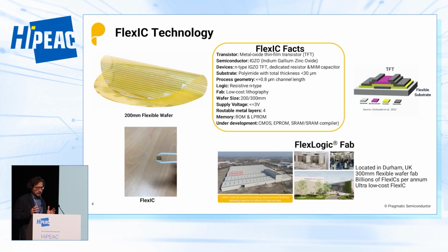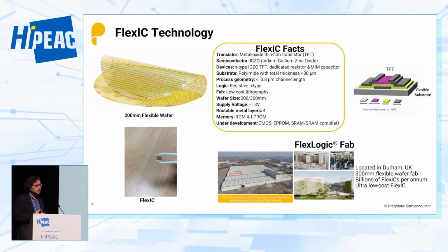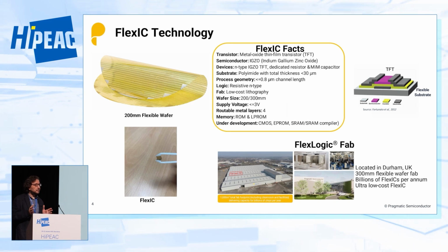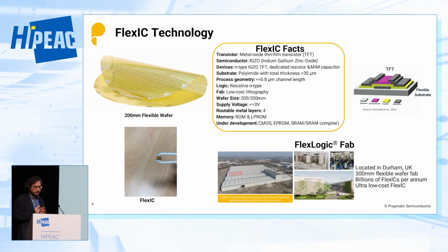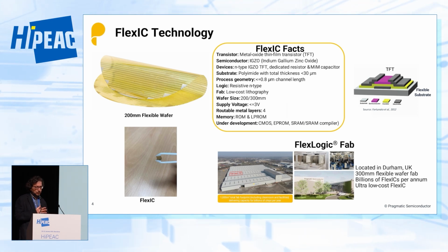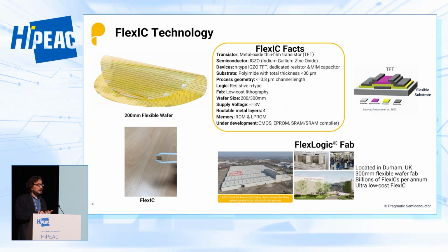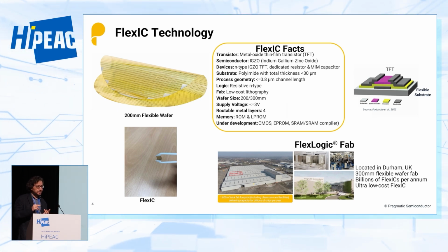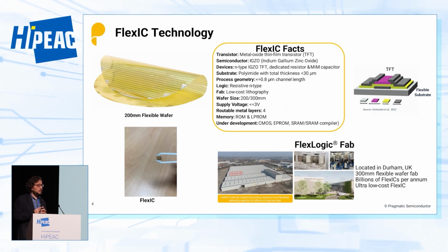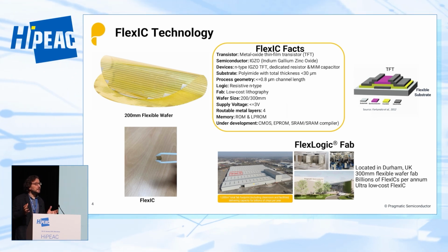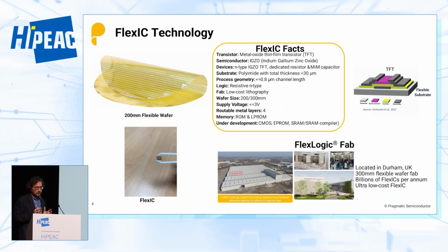We have devices like N-type transistors, based on thin film transistor technology, which is slightly different than the conventional MOSFET. You can do transistors, resistors, capacitors, so you can build logic and any type of digital, analog, or mixed signal circuits with this process.